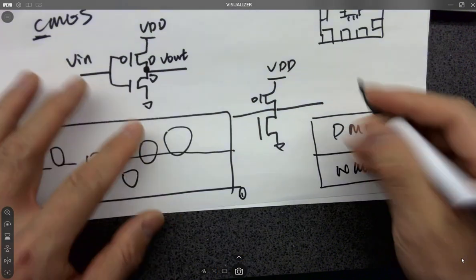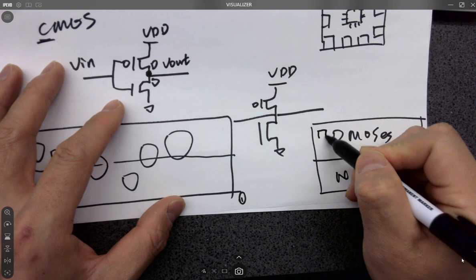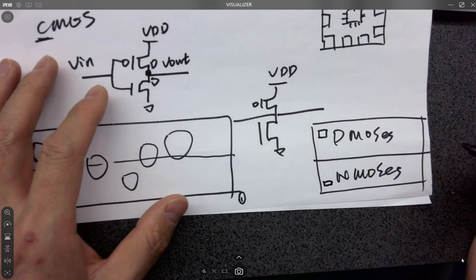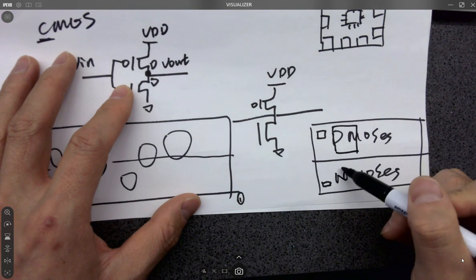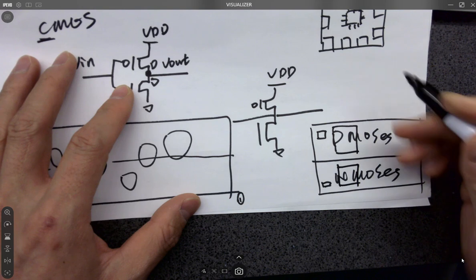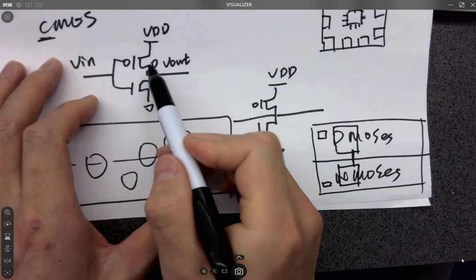So for example, some of the NMOSes don't take too much space. The PMOS is only this small, NMOS is only that small, right? Even though there's a bigger circuit, the PMOSes are that big and NMOS is that big. So it makes sense that we have a line in the middle, and they are making connections in the middle for the drain, right?